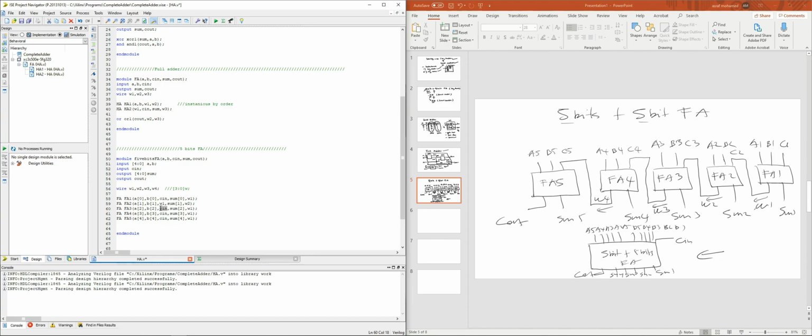W2. Here we replace with W3, and here also the same W3 wire. One wire's output is going to be the input for another. Then W4, here also W4. Finally, you can see the sum and C out. That's all, finished. It's quite easy, right? Now try to see here, the 5 bits full adder hasn't appeared yet.